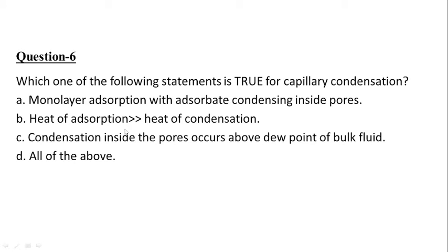Option D, all of the above. So what is the characteristic of capillary condensation? We know that in capillary condensation a multilayer adsorption with adsorbate condensing inside the pores happens, but in option A it is given monolayer adsorption with adsorbate condensing inside pores. So option A is incorrect.